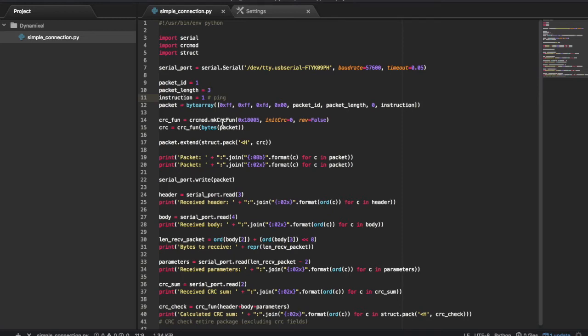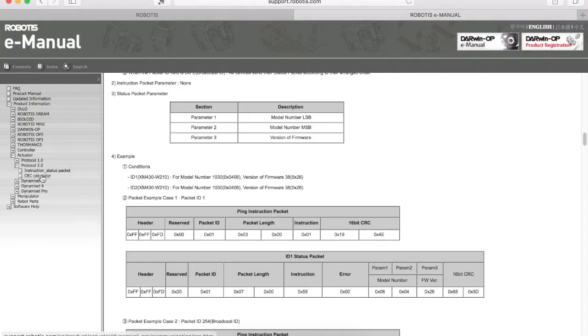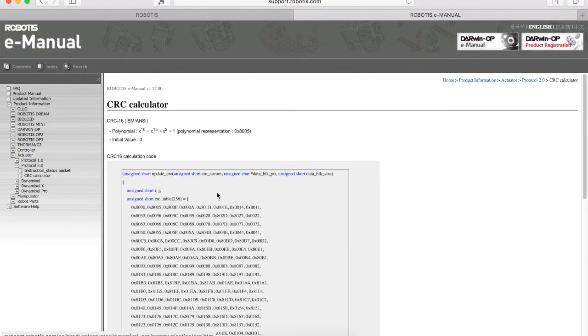There are several different CRC checks, and there's a CRC calculator here. It says that it uses CRC-16, that is a 16-bit CRC check, with the IBM ANSI standard. They also provide the generator polynomial, which is x^16, x^15, x^2, and then 1. If you want to dive into it, look it up on Wikipedia or stuff like this to figure out what the generator polynomial is.